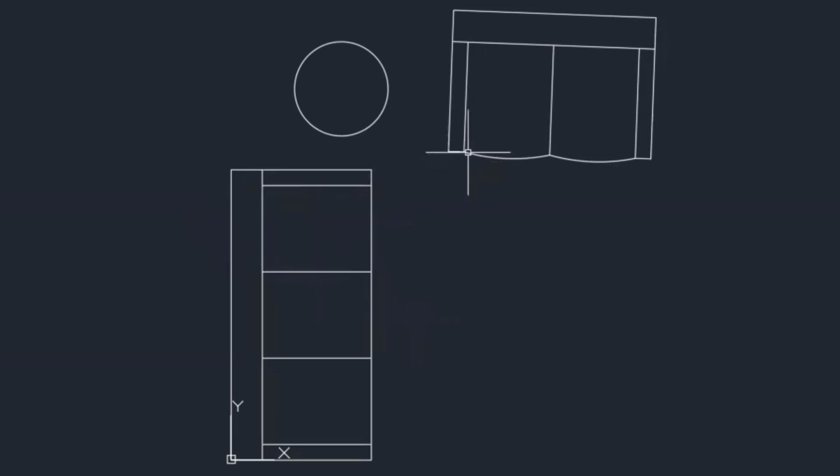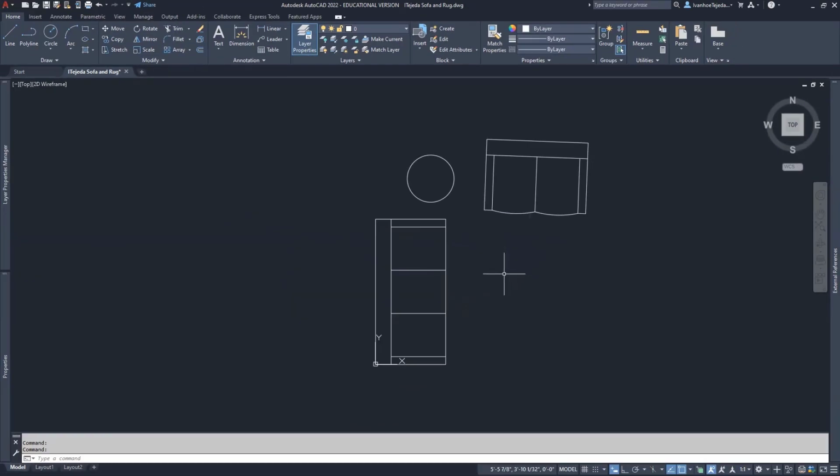When I used it to make my 2-seat sofa, I decided that I was going to make a copy of it. And when I made a copy, for example, I'll come over here to copy, I had to window everything like this. And I selected, as you can see down there, 9 objects. But I'd like to take these 9 objects and convert them into one single block that represents my 3-seat sofa. Let me tap the escape key and show you how to do this.